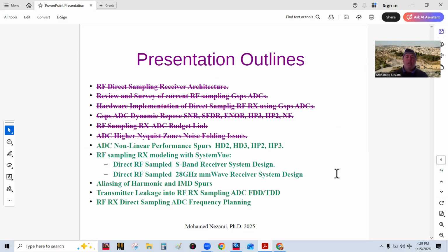Now, realize up to this point, we have not incorporated spurs and harmonics due to the interleaver process of the ADCs.